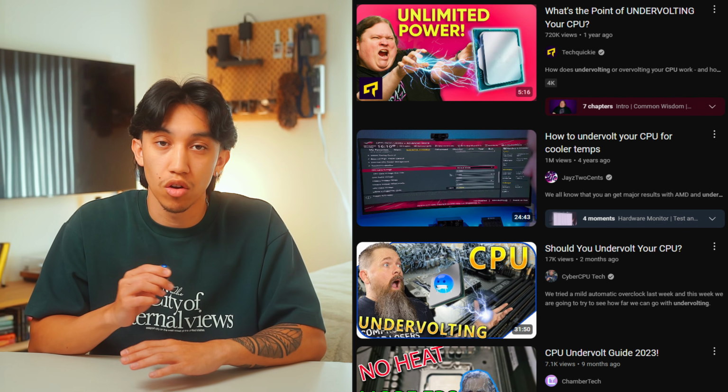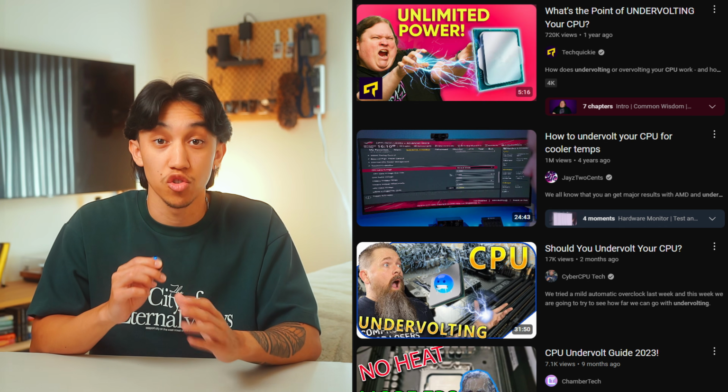Through the process of this build, I've come up with 4 solutions. The first one is that you can undervolt your components so that they produce less heat. There are tons of guides all over Reddit and YouTube on how to do this, so I tried it, and it did help, but the 13700K is just such a hot chip. It was still thermal throttling under load, and that's just not something that I was comfortable with leaving. But for those of you who may have slightly less power hungry chips, undervolting could be a perfect solution for you.